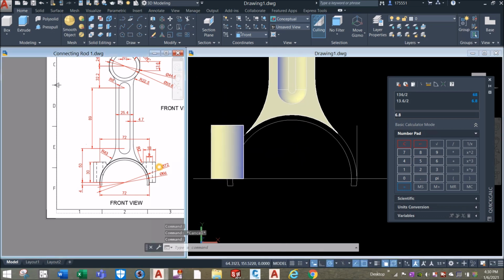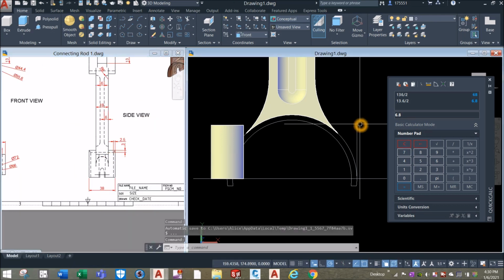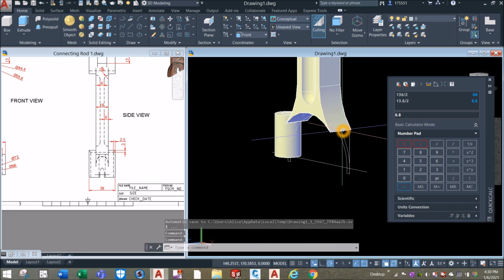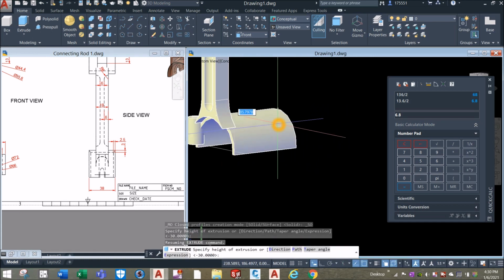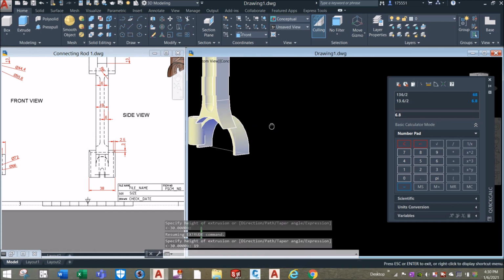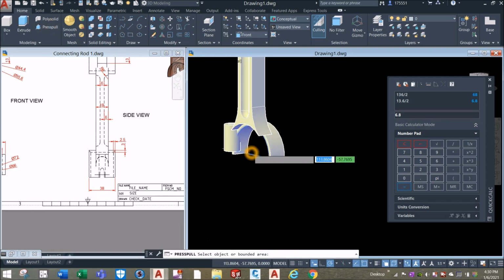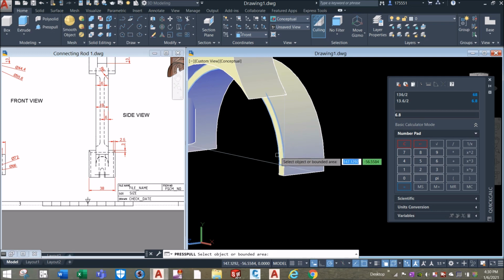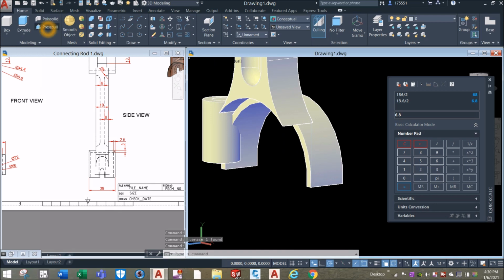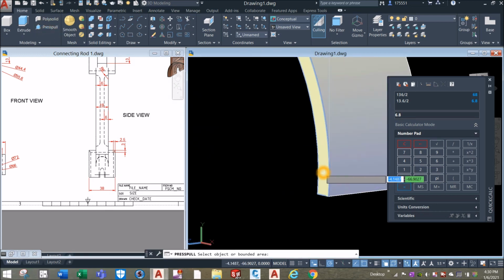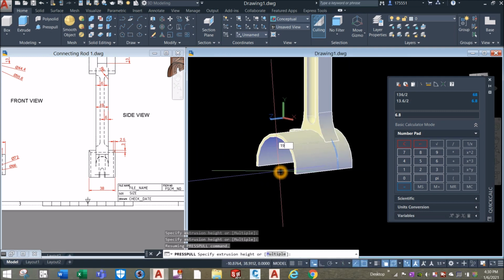Now I'm going to extrude this object, and the thickness for that is 38. So I'm going to extrude it for 19 units, halfway of this thickness. Extrude to that direction for 19 units. And then hover over this portion, use press pull command. I'm going to delete that first. Otherwise, it won't work. Hover over this portion and pull this one for 19 units.